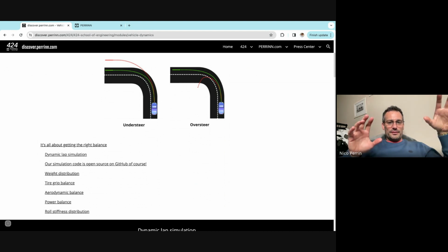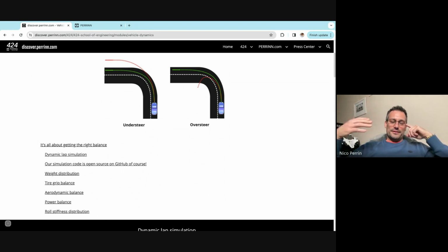So I will talk understeer, oversteer. I will talk balance today. And there's been a huge amount of work done to get a very good balance of 424 around the Nürburgring, not only in the middle of the corner, but from the start of braking, and the braking is very aggressive, to effectively the apex, and then on the exits when you're going back on power. And all this sequence, we call it in engineering terms in motorsport braking, late entry, apex, and exits. And all these sequences have to work together and be connected, if you like, in terms of balance.